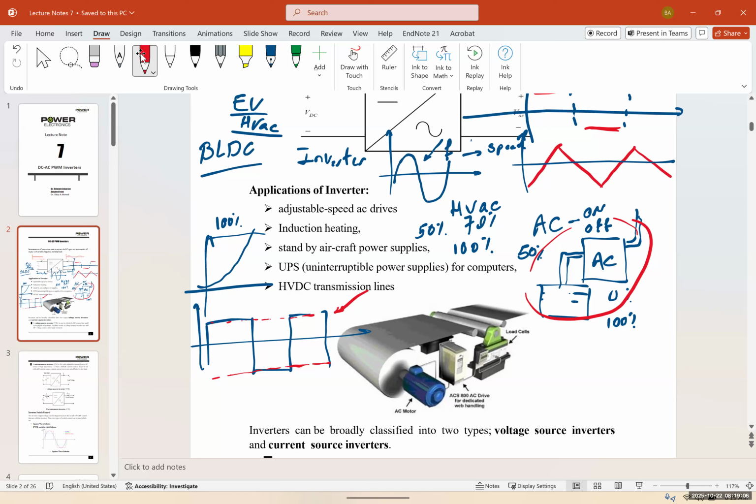And sometimes you even see a spark. Why? Because when you have a square signal, you suddenly go from positive voltage to negative voltage. So you're changing the polarity immediately, and that damages the AC compressor. And again, it may work for a week or two, but it's going to get very hot very quick, and most likely you're going to damage it.